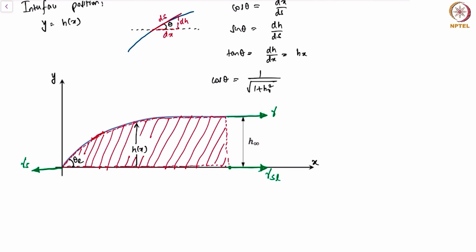Are there any other forces present in the problem? Yes, we are considering a situation where gravity is important, so gravity is downwards, and as gravity is important, the pressure across the thickness of the puddle will vary. So in other words, there is also a gravitational force, hydrostatic pressure, and this hydrostatic pressure is just acting this way. This is P, the hydrostatic pressure.